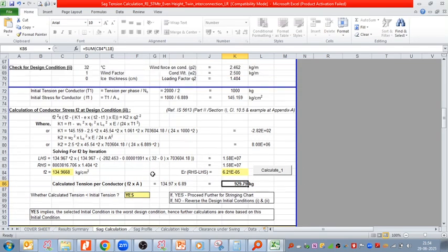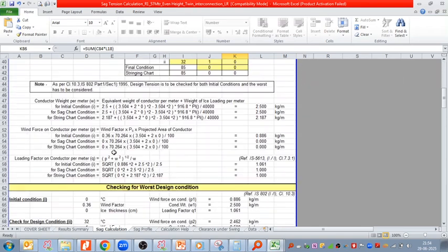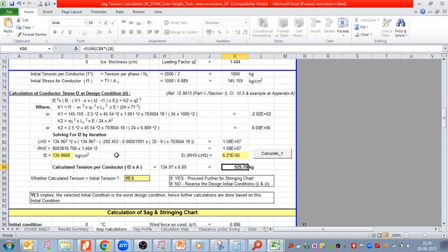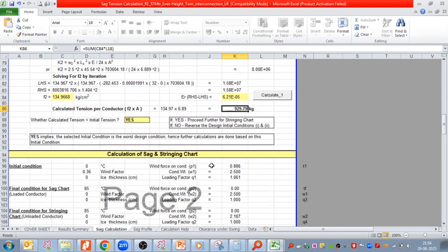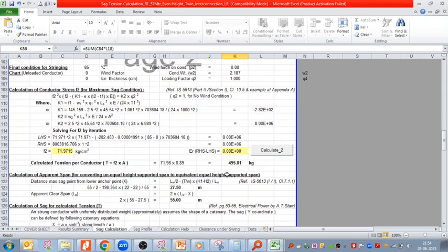As you mentioned, instead of taking this one, we can first put the span length in my sag tension calculation Excel, then take whatever final tension comes, based on the temperature, and put that there. In that case, instead of 1000 kg, it would be 929.6 kg, or 930 kg. This could also be one method. Okay, thank you, sir.